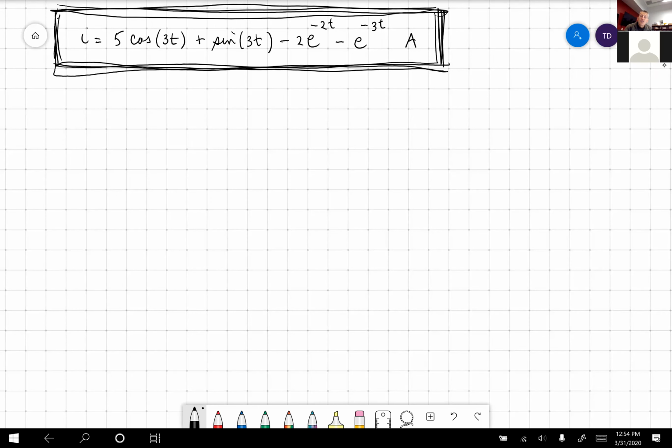So again, I didn't use the mixed mode method. I could have written one KVL equation, one KCL equation. I did not do that. Instead, I opted to write one integral differential equation there. Sometimes when you do that, you'll end up with a third order differential equation. Then you'll have to integrate that equation back down to get a second order differential equation. So I tend to stay away from that for the most part, but the series RLC circuit is a pretty easy one. And for that reason, I opted to write that equation because I didn't think it was going to be cumbersome.